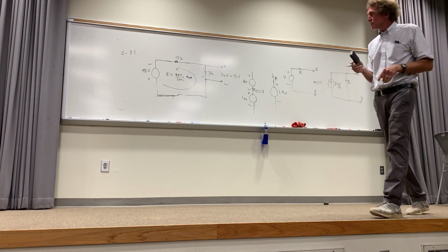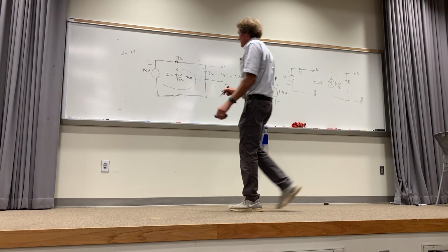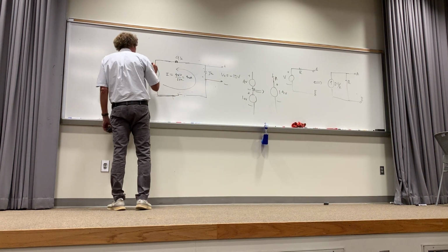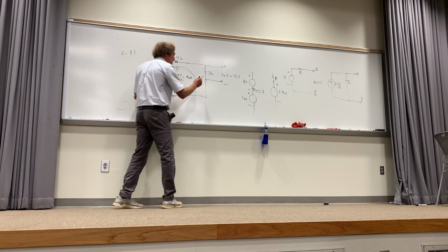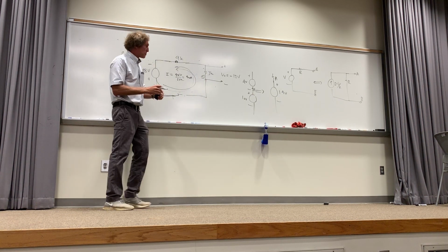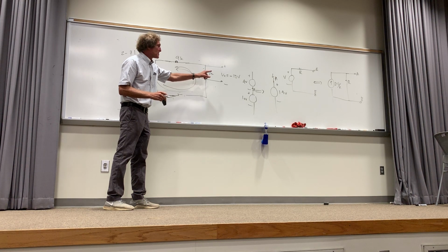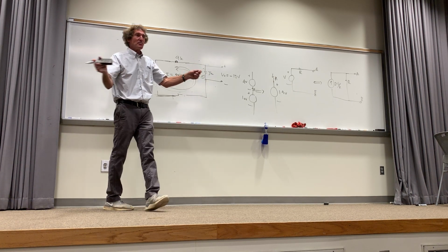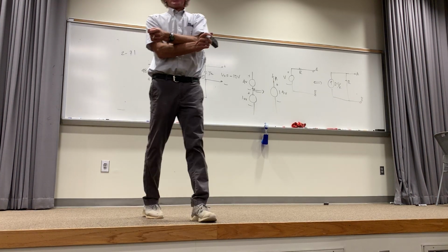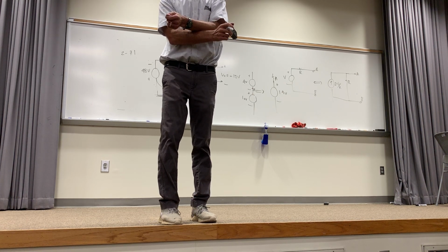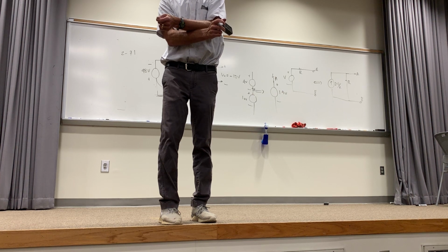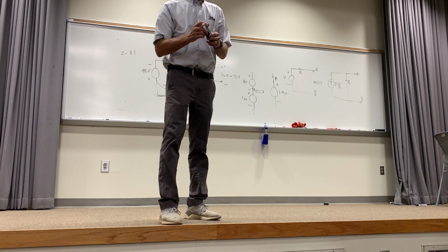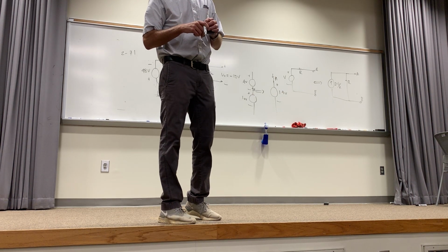Yeah? Why is it minus 12? Well, you see how this is 48, this is plus to minus, right? Current is driven this way, right? Okay. That means positive current enters a positive terminal. It's plus to minus. So the actual measured voltage is like turning the leads in your meter around. And if you've ever measured a car battery wrong, you get a minus 12, right? That's basically what they're getting here. They're getting a minus 12. That's it. Other questions about that?